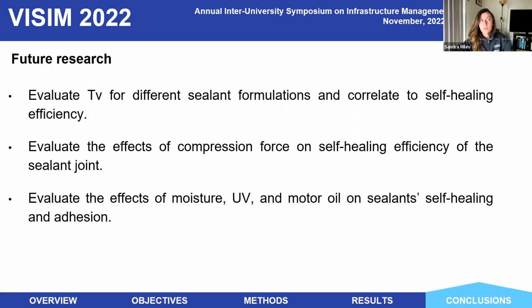Yes, the service life now is about 10 years. And for this one, we can just assume that it's going to improve, but that's the idea. For example, in the joint, during the summer when the temperature increases, the joint is going to shrink, and that is going to apply pressure on this self-healing sealant. So if there is a crack inside, then the two surfaces where the crack is are going to close, and then these bonds can reform, and that's basically the self-repair that we want to see.